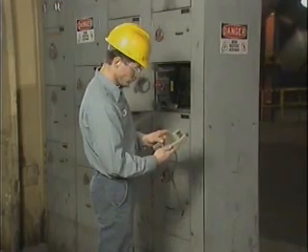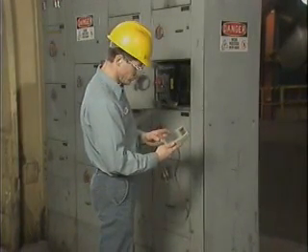We'll begin by looking at how a de-energized controller can be tested for grounds. Although one ground in a controller circuit is measurable, it has little or no effect on the normal operation of the controller. However, if two grounds occur in the same circuit, the result is a short. When a short is caused by a ground, normal controller operation is affected. So when the symptoms of a short are present, it's often necessary to test the controller for grounds.